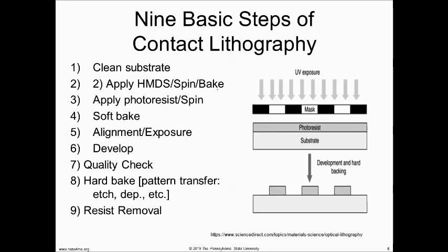So what we're doing with the photoresist is defining that process step. And then importantly, sometimes people leave this out. Then the resist, we don't need it anymore, because we did my procedure, etch or deposition. We have to remove the resist. Does everybody see that? So in some crazy conceptual way, we really want the resist, and we're using the resist, but after we're done using the resist, it's kind of like an empty water bottle. It becomes something that we have to recycle or get rid of. Does that make sense? It's of no use to us anymore. That packaging or that layer, we have to remove. So the resist itself becomes a potential contaminant for the next step. So we have to remove it, really.